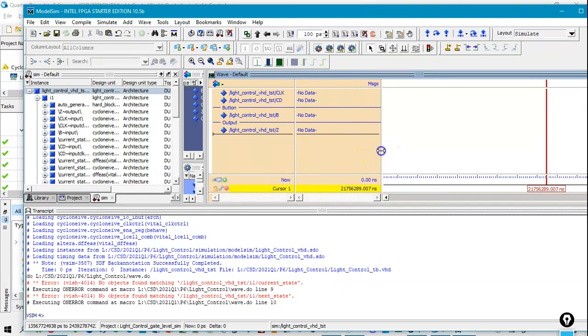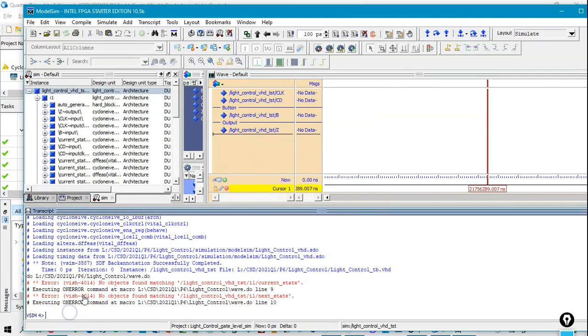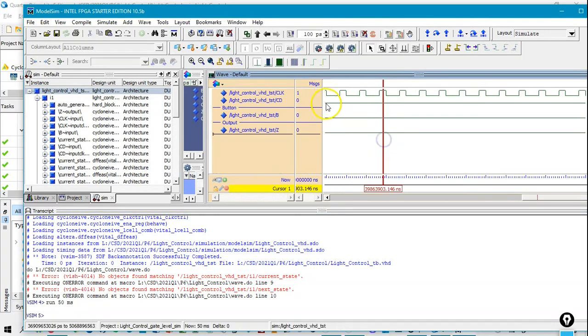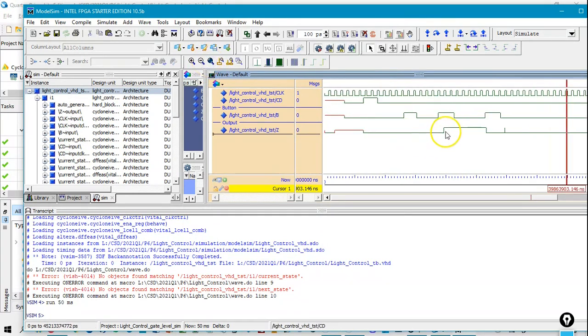So now let's run that thing. Let's run for 50 milliseconds. That's it. So you see the clock and the full picture. You see everything goes fine. One pulse, one clear direct, and then you see the output is very clearly undefined until you click the clear direct. So now while clicking the clear direct, even if it takes several clocks, which is the normal situation, nothing happens, and then the system goes to the stable state idle until one click and another click.